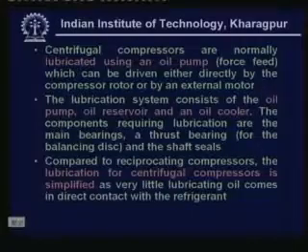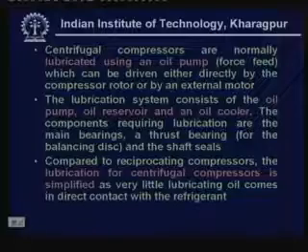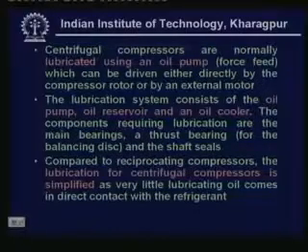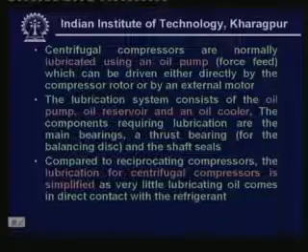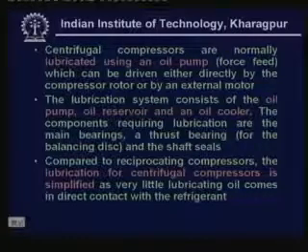However, compared to reciprocating compressors, the lubrication for centrifugal compressors is simplified, as very little lubricating oil comes in direct contact with the refrigerant. So, you find that the design of lubricant system is not as complicated as in case of reciprocating compressors, because normally they do not get mixed in case of centrifugal compressors.